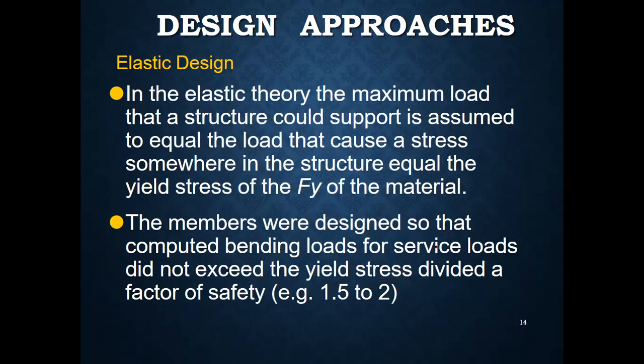In the elastic design, we assume that the maximum load that the structure could support is equal to the load that causes a stress somewhere which is equal to the yield stress of the material. And then these members were designed using the bending loads such that the service loading does not exceed the yield stress of the member divided by the factor of safety.